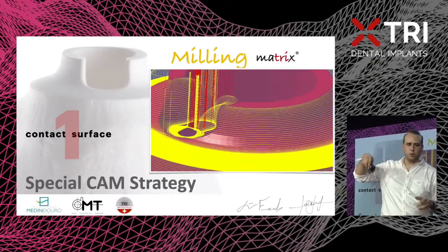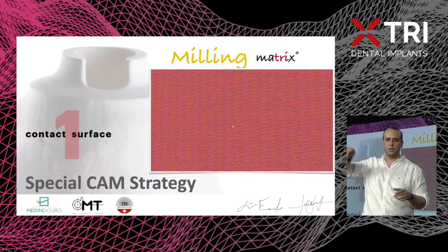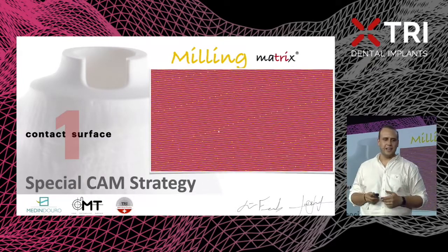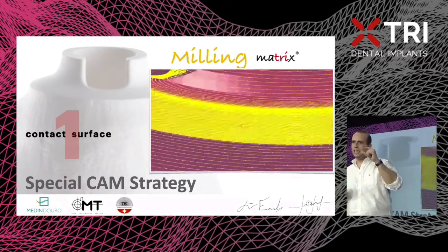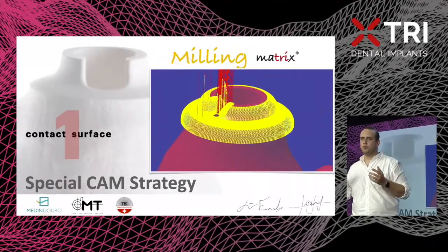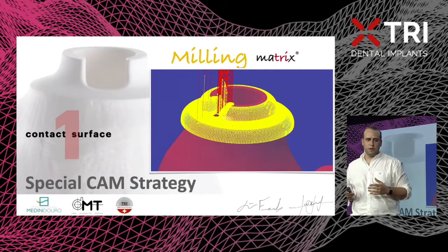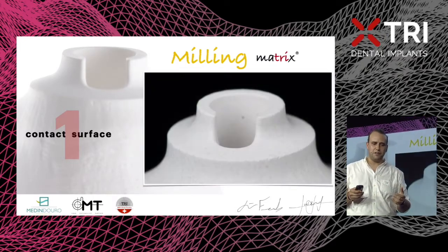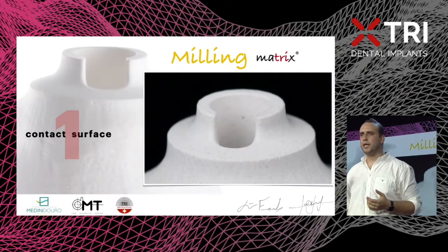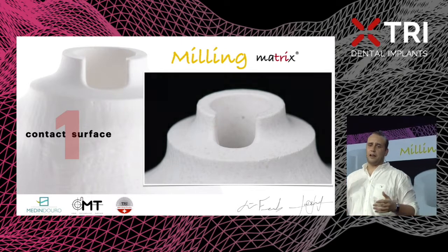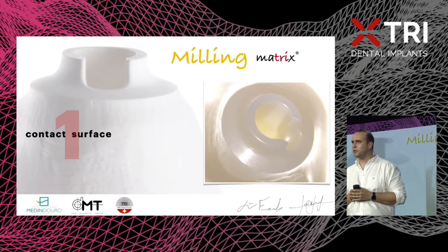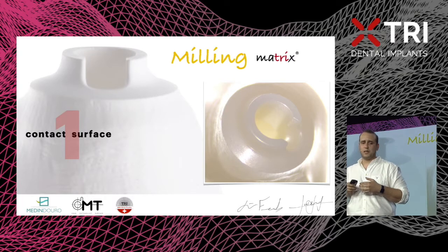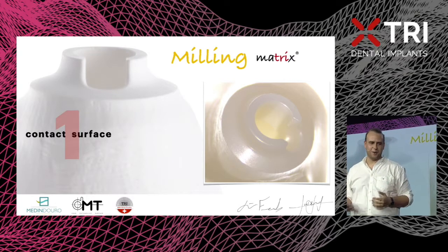the way of the tool, those lines are the way of the tool, and the amount of the ways of the tool. The space between those tiny lines is about 0.02 millimeters. So after that, we can achieve a result like that before the sintering, okay? And after the sintering, we have a shrinkage of about 20% of the zirconia, so the precision is increased a lot.